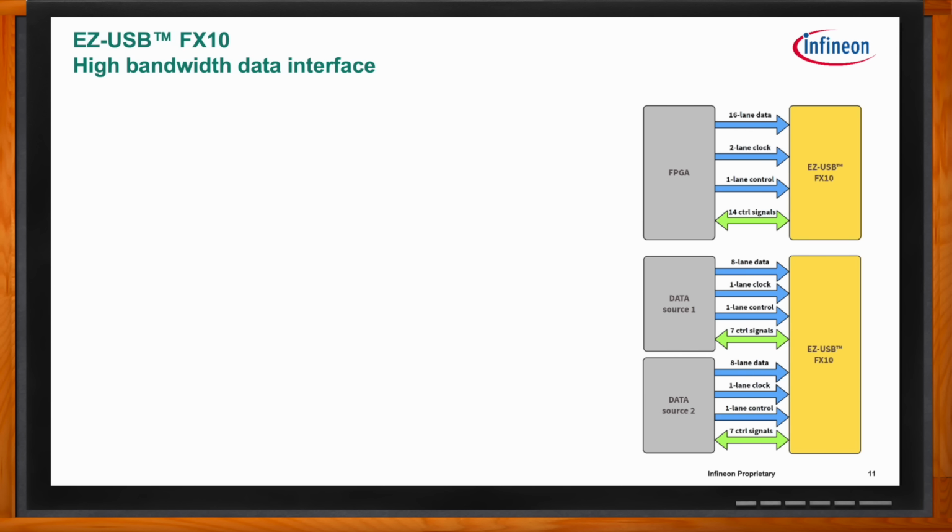First of all, in LVDS mode, we only provide one direction of traffic, which is receiver only, because the data is coming from the external source to the USB host or to the PC. Data acquisition applications require high bandwidth and probably represent 99% of the applications out there. That's why we only put the receiver into LVDS mode to optimize that usage.